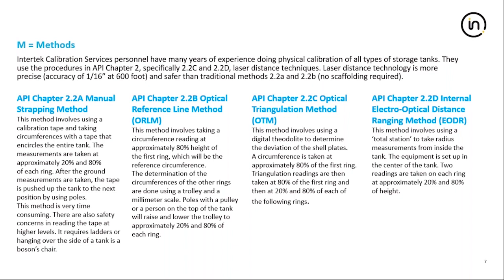So all of the other methods that we see here, 2.2b, 2.2c, or 2.2d, we go all the way to J or H, if I recall correctly. All of those other methods are just methods for estimating the cylinder volume, but the 2.2a includes not only the cylinder volume estimation, but also the procedure for calculating every other property that you require for creating the gauging tables.